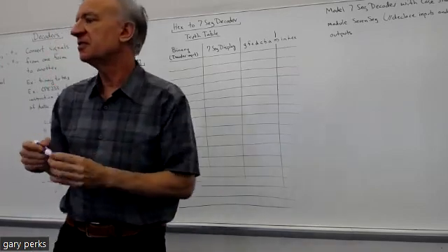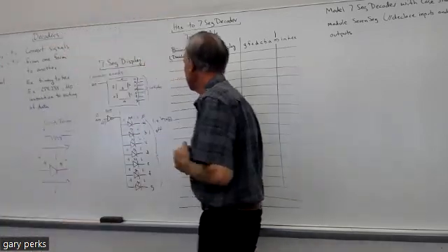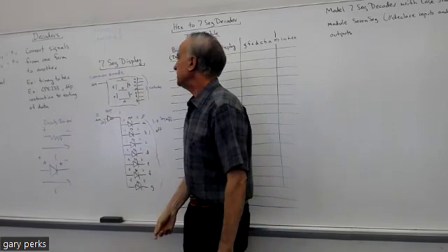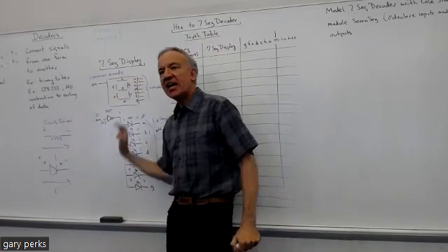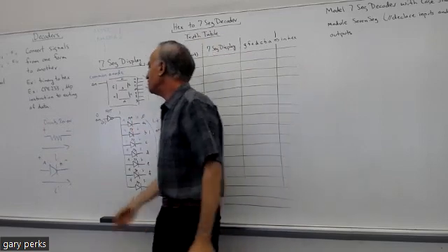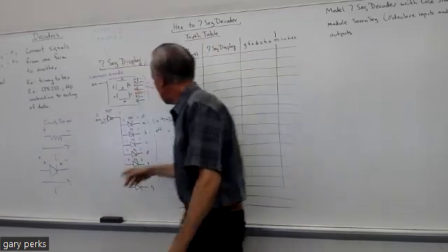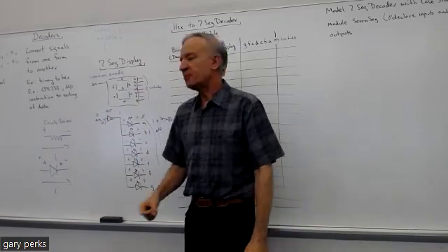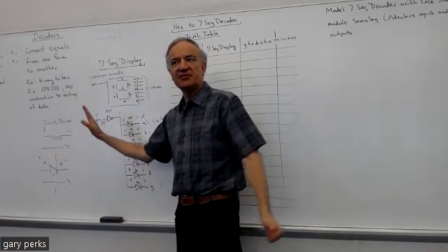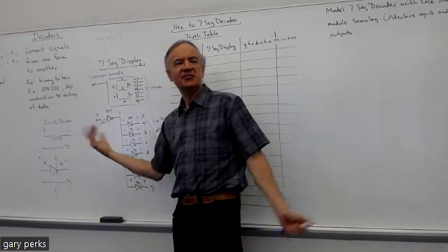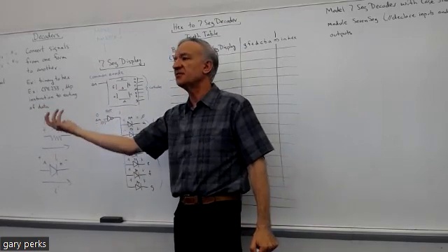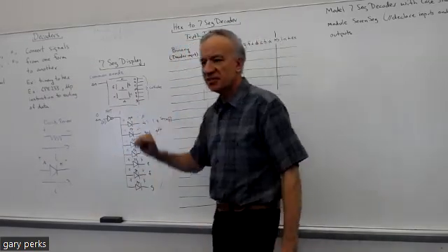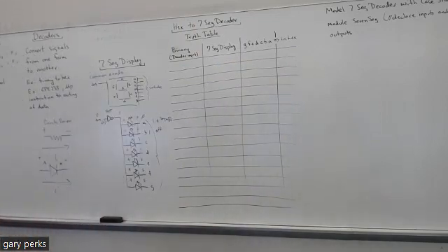You had a question earlier about the NOT gate. I don't think it's absolutely necessary to know the innards of how the display works. If all you knew is that you have to make the anode a 1 and the cathode 0 in order to get a segment to light, that would probably be good enough. But I felt that for some people it would be helpful to know some of the details, especially if you had circuits, because it ties into stuff you've learned in other classes. Any questions on the 7-segment display before we move on?